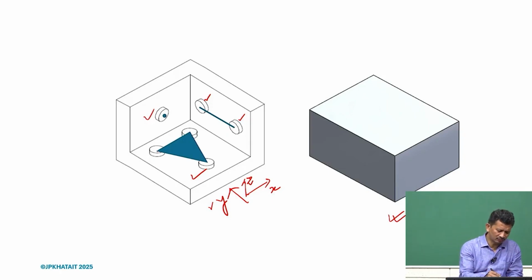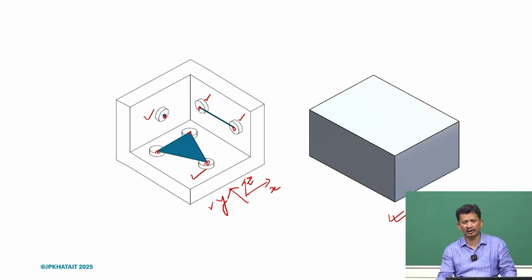Of course, what is the assumption here? What we try to highlight here is that this contact should be made all the time, should be there. So of course, we need some way to make these contacts possible. What we later refer to is the nesting force. Some kind of nesting forces will be required, or we can use bolts and whatever is required to maintain those contacts. What we realize here is the location of this object with respect to the wall is defined.